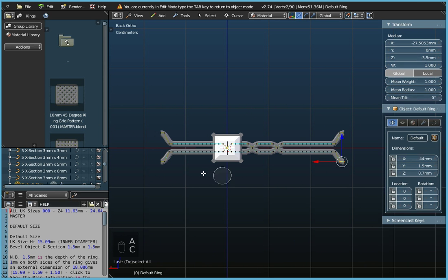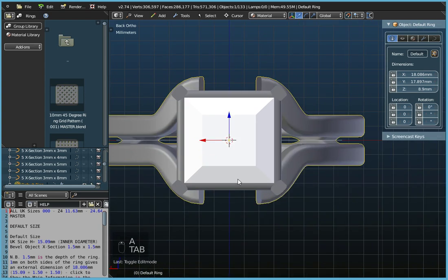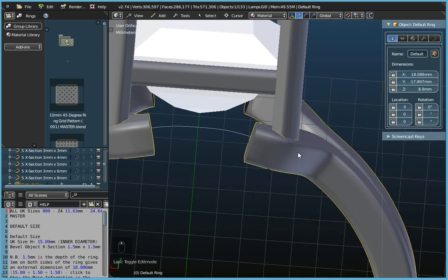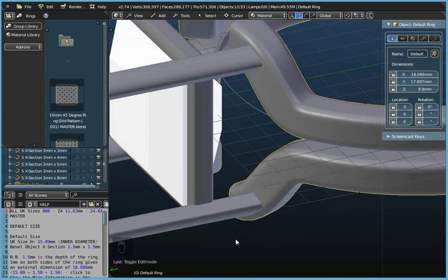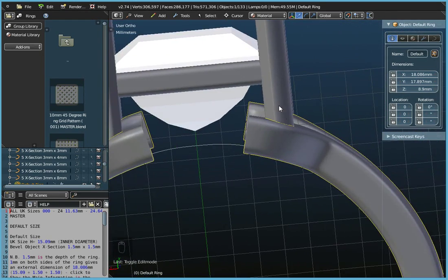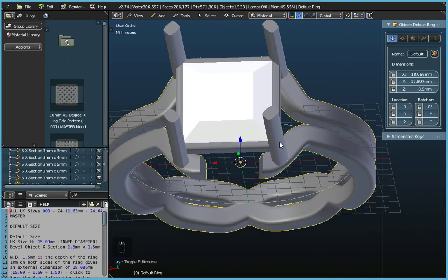And we'll do the other side as well, and so this is going to be minus 3.7, so we needed to move it down, which I've done. So now my prong should be fitting quite nicely in the end of the ring shank there. Now there are other ways of doing that. We could have moved the bottom of the shank and tilted it slightly, but I'm going to keep it vertical.